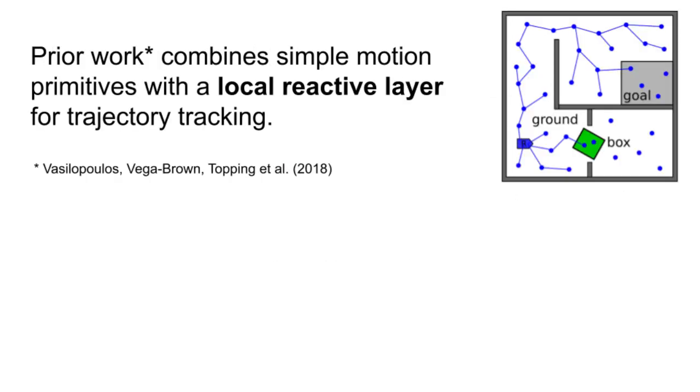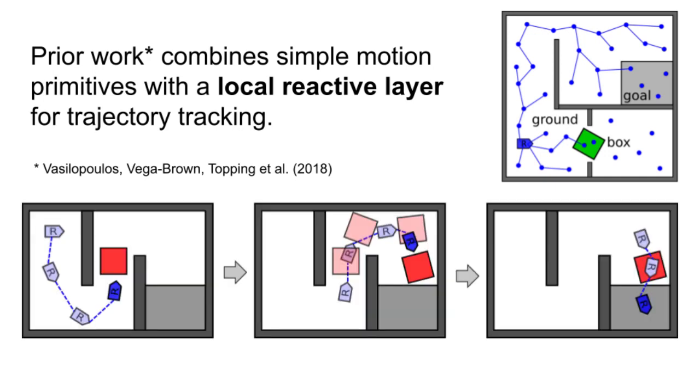In prior work, which we use as a baseline, the deliberative planner performs integrated task and motion planning using simple straight-line motion primitives. The feasibility of actions is thus determined by evaluating collision checks between sampled poses. Resulting plans consist of potentially long sequences of actions. The reactive layer is only used locally for tracking of the resulting path and handling unexpected obstacles along the way.